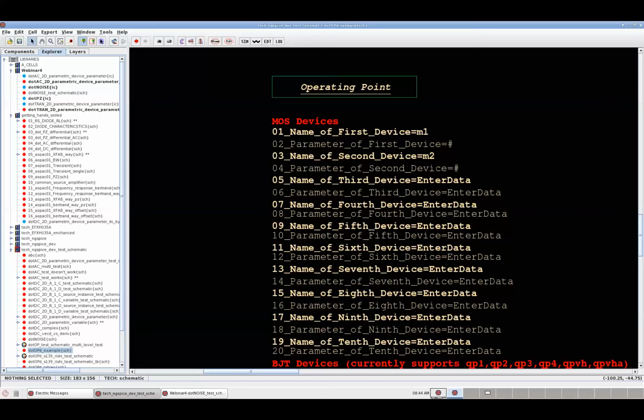Yeah, there is no generalized template. It's better to write a SPICE code, because you first do .transient and then use a measure statement, and when that condition is met, you ask it to perform AC analysis based on the OP saved at that value.